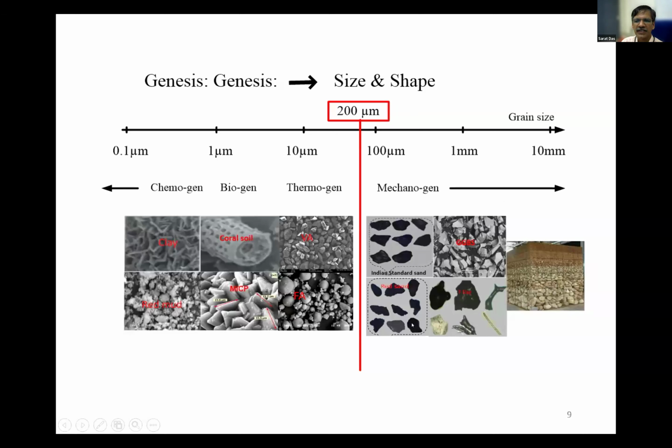These are coarse grained. But coming to the fine grained, we have volcano ash, which is through thermal and natural genesis. But with fly ash, the coal is burnt at 1300 to 1400 degrees centigrade and it is generated. So when I compare this, I am talking about volcano ash as a pozzolanic material, and I am also considering fly ash as a pozzolanic material. So that has tempted us to put it in cement and concrete.